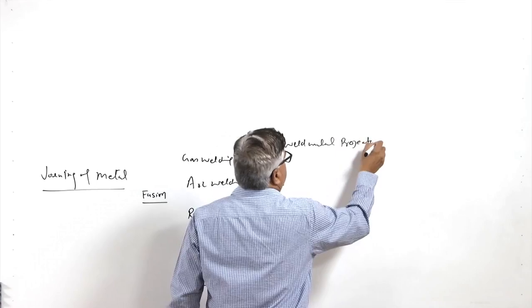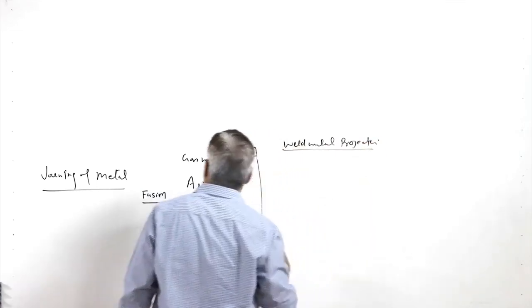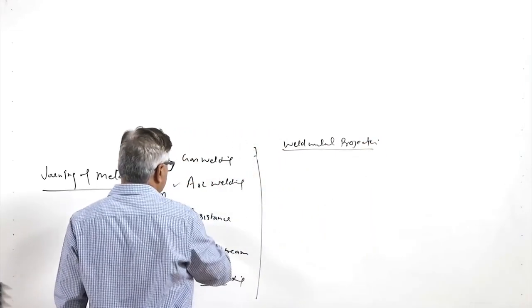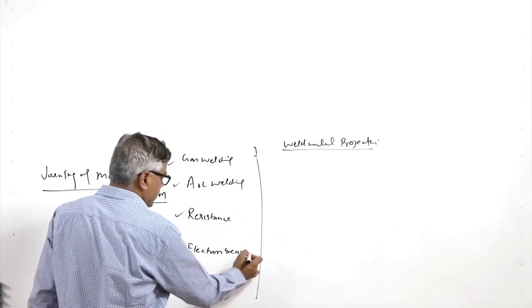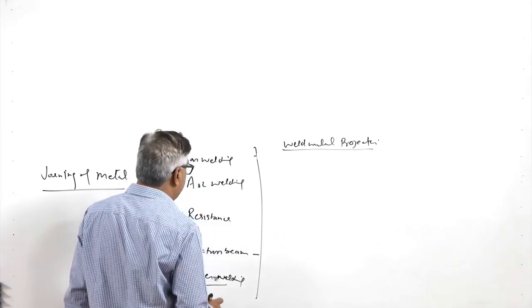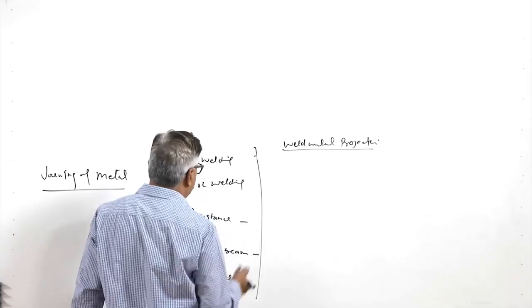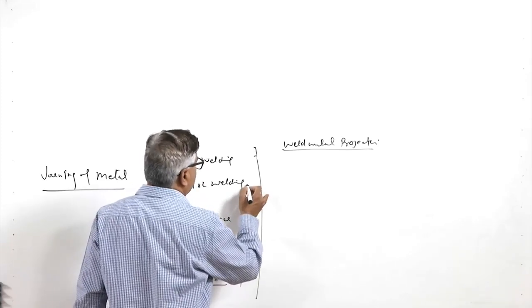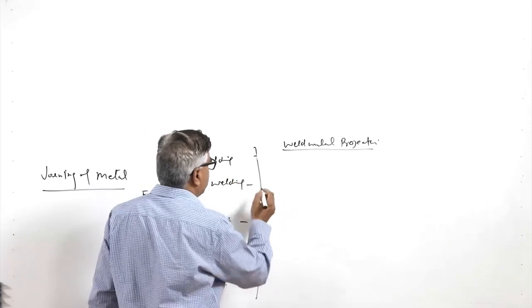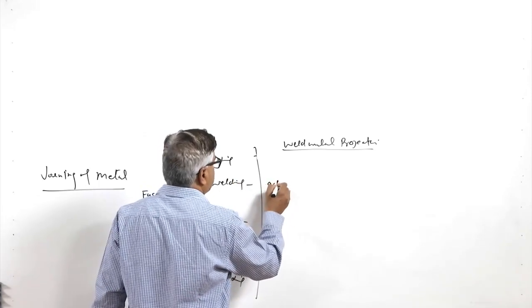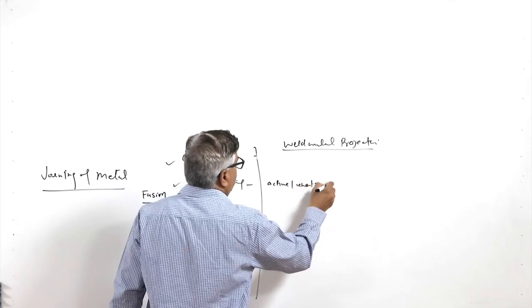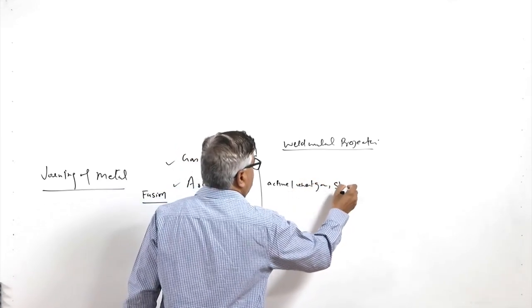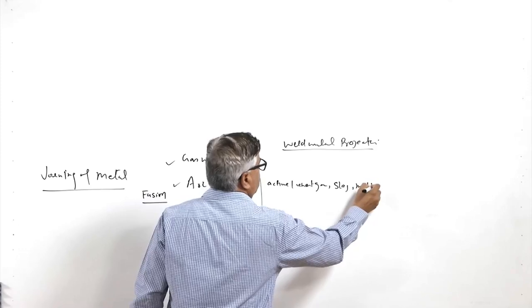Since the different welding processes work on different principles of weld metal protection, for example, electron beam welding uses vacuum, resistance welding is normally done in the environmental conditions, and arc welding uses different approaches like the active gas or inert gas environment, or the slag, or the molten flux.